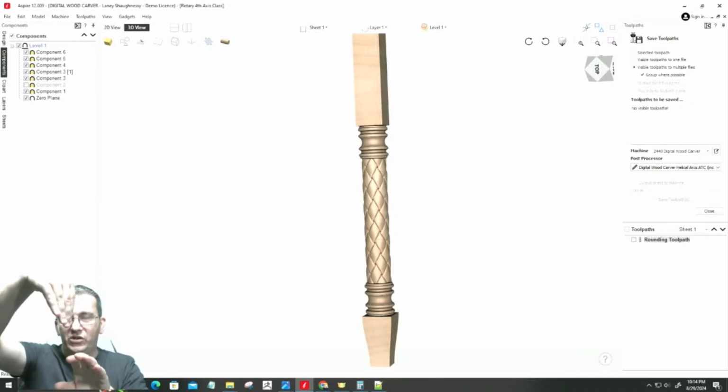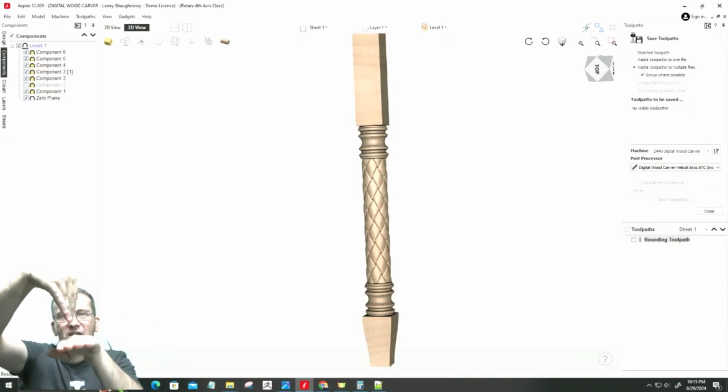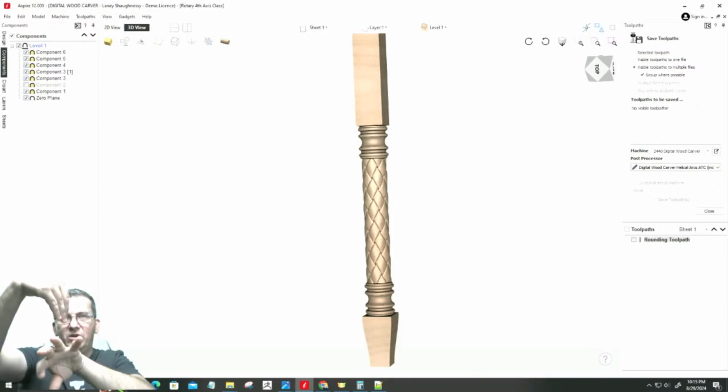What the post processor assumes when it converts one of your letters, X or Y, to A is that you're centered over your stock and that doesn't move. You only move back and forth along the length of that stock while that stock turns. So if my x-axis moves back and forth along my stock, those are the values that get put out. My z-axis goes up and down to carve the stock, and those values get put out. But the y-axis stays in the center. It doesn't move, but I have rotation. So in Vectric, that movement is the y-axis in this case, but it needs to be converted to A, so it turns all the y values into A values so that the rotary turns.